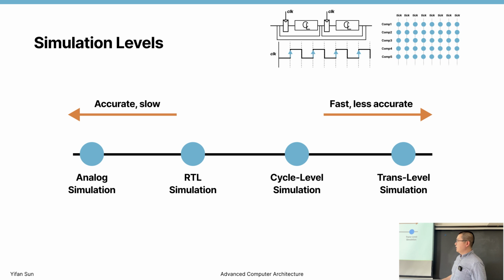So that's RTL, the register transfer level. So what is register transfer? It's basically you have a register, right? Then at every cycle, you pass the data, update the data, and either transfer back to this group of registers or transfer to the next group of registers. That's why it's called register transfer level simulation. Then it's either cycle level simulation or RTL level simulation.